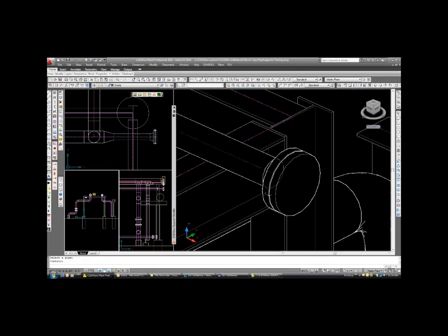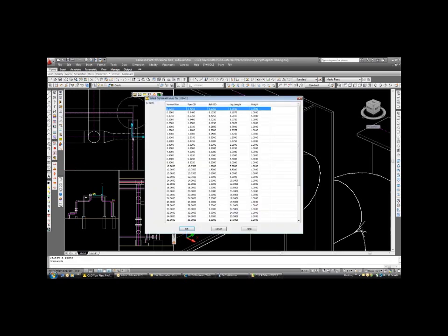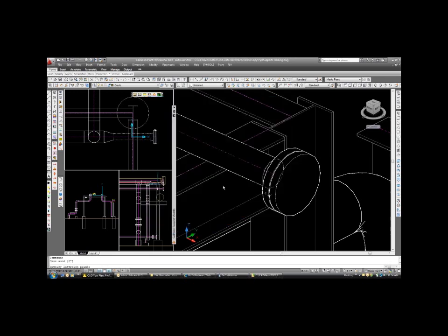I'm going to select the 3-inch part of this line to demonstrate to you that you don't need to reset the size or spec or anything else. I have a setting here that will let me pick optional U-bolts, and I will show you the setting in a minute on the support file. That will let me pick other settings other than the one. If you just select OK at this point, it will automatically pick the size that we want.